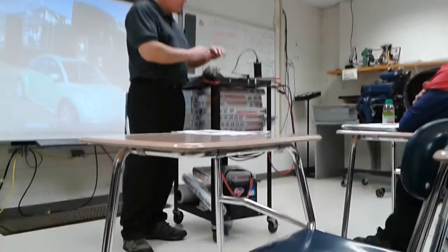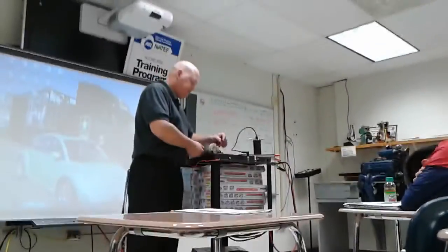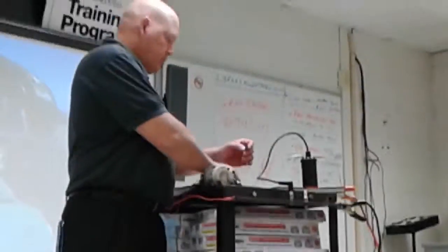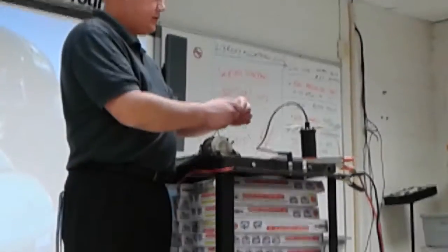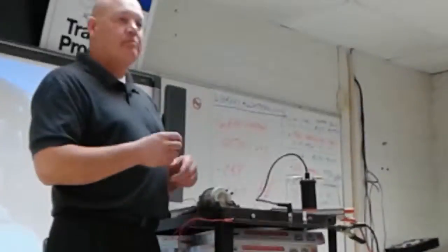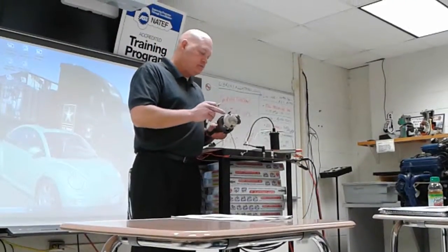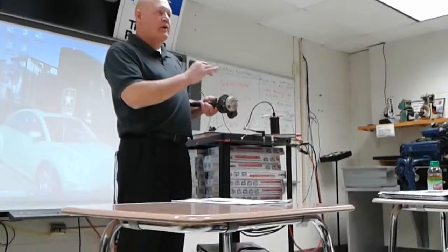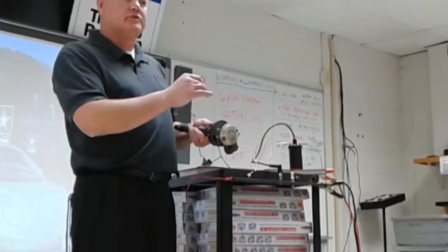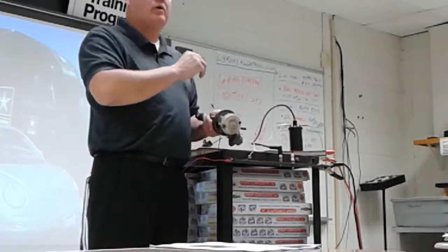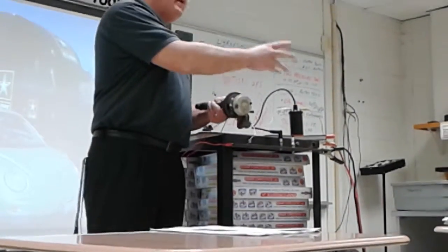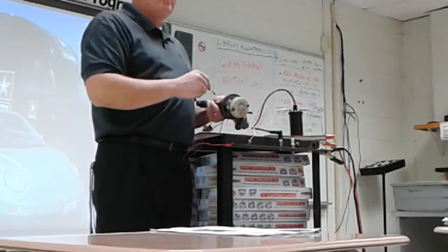Now on the old cars, we used a device called a distributor. This is going to go like this. And this is a little bit like what the book is talking about. You guys were talking about condensers, breaker points, and so forth, right? Okay. Inside here are some little breaker points. This little breaker point is going to be the switch that opens and closes to either close, let current flow, build up the magnetic field, or open and let the magnetic field collapse, and then we have the big spark.